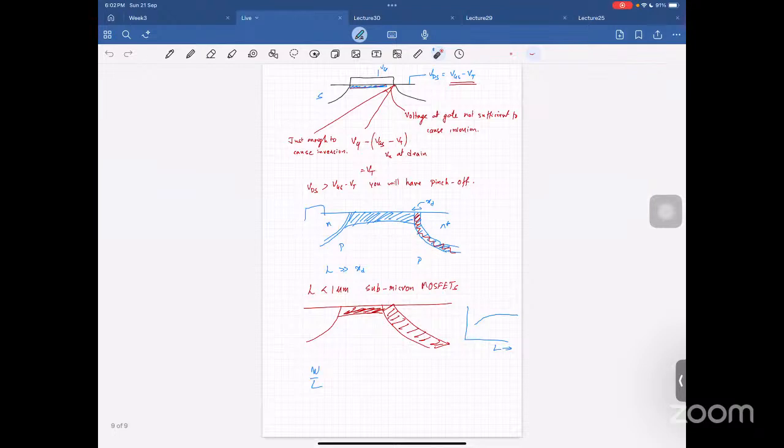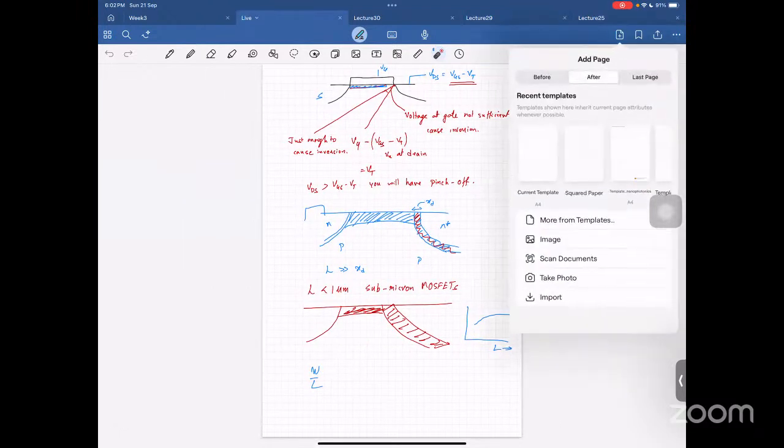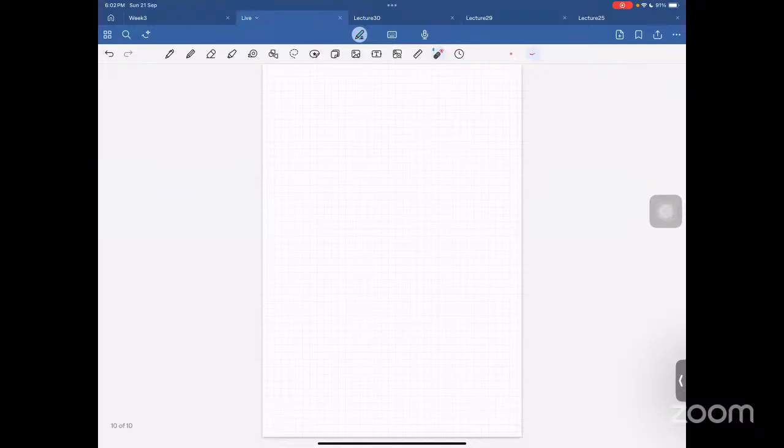This is very, very important for design, because when you're designing a transistor, what we're teaching in this course is very simple. W by L is this much and all that, right? Simple first square law model. But very soon you'll see that for 25 years at least, even more than 25 years, the transistors don't exactly behave as what we are describing. Short channel effects is one part of it, but there are a lot of other effects that come into the picture.